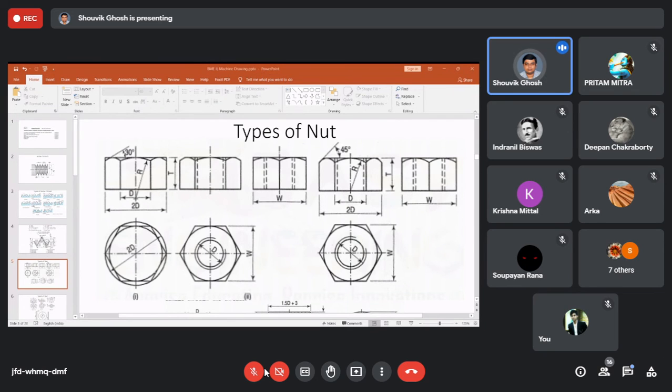Oh, okay, my bad, my mistake, sorry. So basically, when you are designing or using a nut, if both the sides of the nut are kept fixed, or I mean not rounded, and they are having 12 edges, as you have in a hexagonal nut, all those 12 edges will generate a huge amount of stress at those tips.